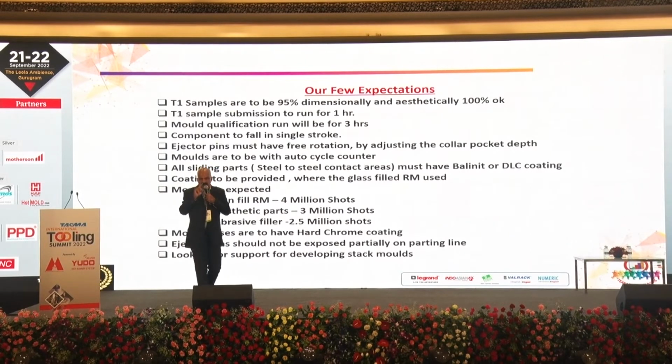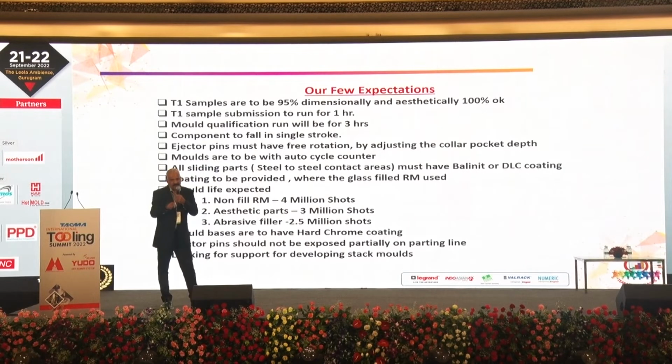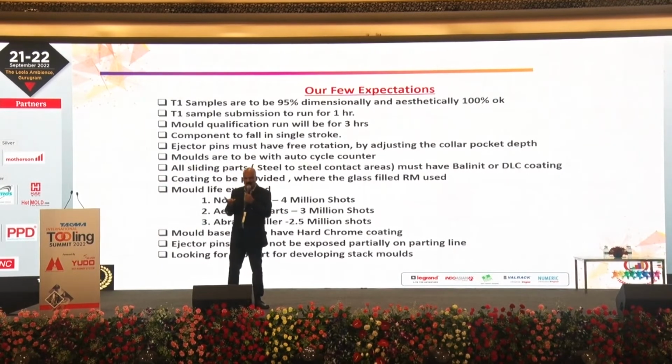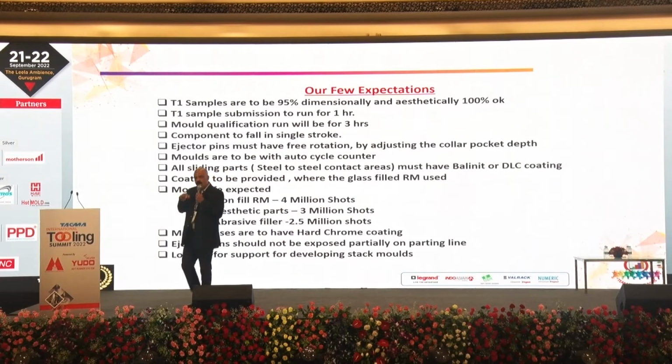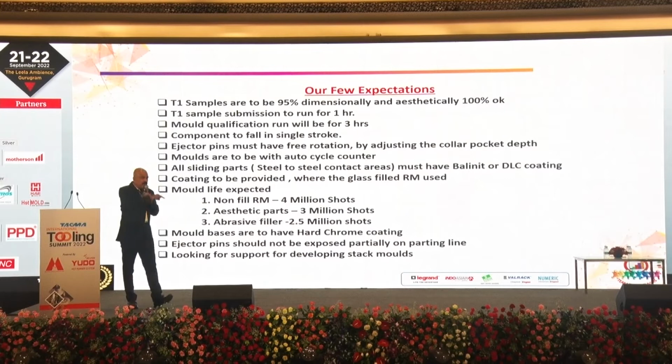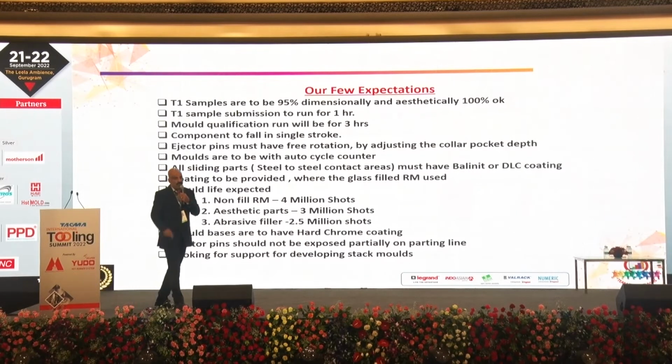Why? The reason is that you will do the process correction for flash elimination and remove the sink marks. You will power pack the mold. That will vary your dimension. What happens? Somehow you will give the component, R&D will approve it. When you go for the buy-off trial, you have surprises. You will not be able to clear it.